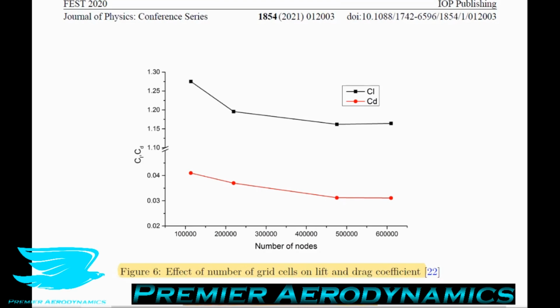These are all of 1 millimeter trip heights. The same pattern mesh is used for respective trip shapes with all other trip heights. The lift and drag coefficients are the parameters checked for the grid consistency. The simulations are carried out at an angle of attack of 6 degrees, and the results for the baseline test are shown in figure 6.